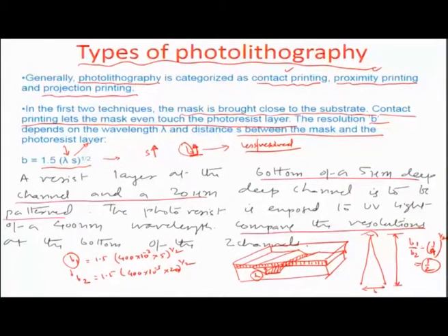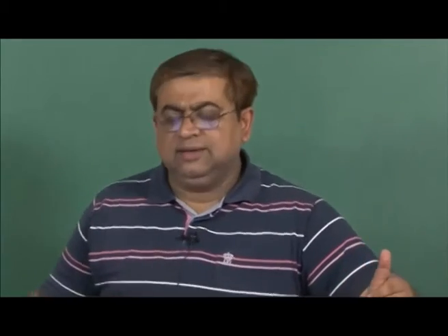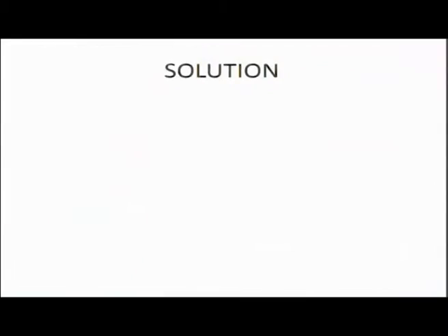Okay. So, the minimum feature size that can be accommodated at a channel depth of 20 microns is going to be exactly twice the feature size that can be accommodated at the channel depth of 5 microns. So, these issues need to be kept in mind while developing mask designs, particularly in the MEMS application. And let us move ahead now into actually how you do lithography.